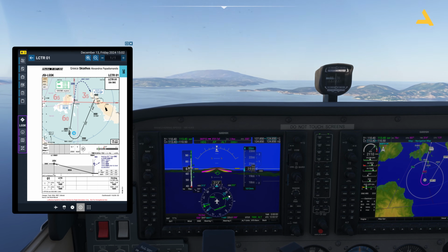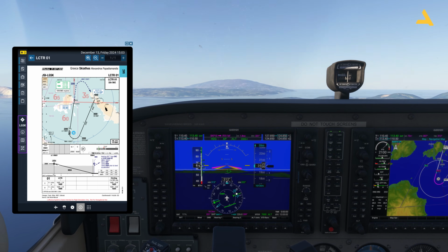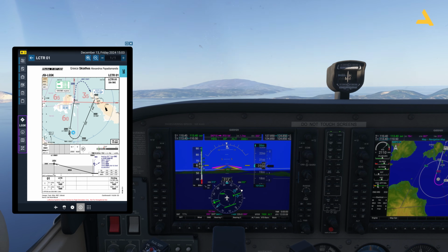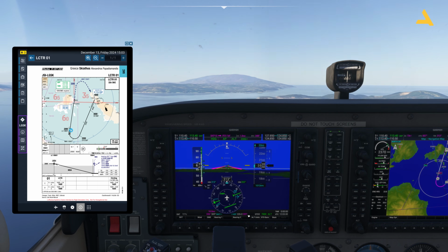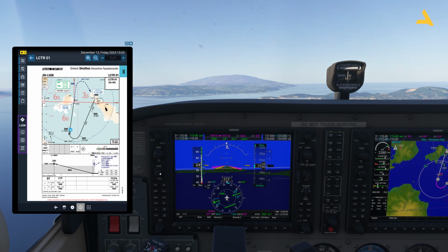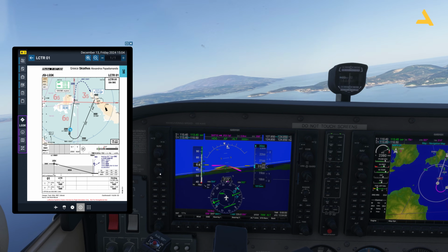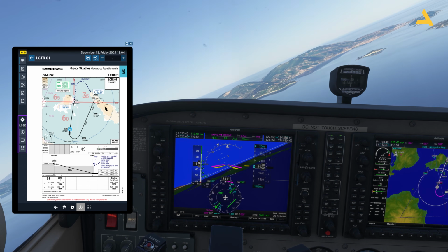Now 360. Soon I will be intercepting this line. You can see this bearing pointer for the NDB moving. It will be somewhere here when I will be turning right, heading 7. Now you can see the numbers over here are changing. 5, 6, and 7. It went back to 4. That was interesting. And now I can start turning to this heading 007, and then you will see the runway.